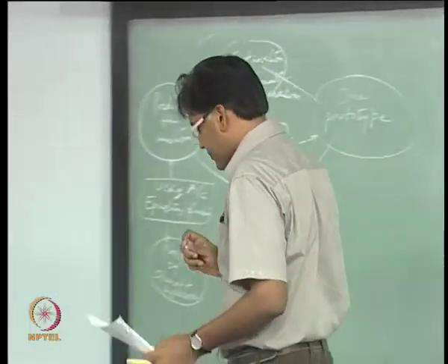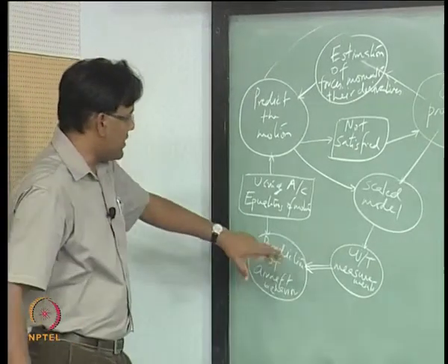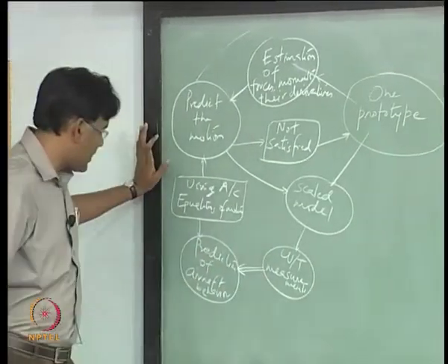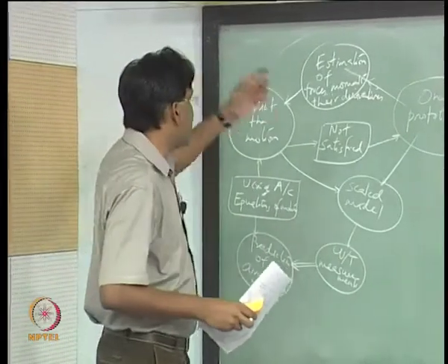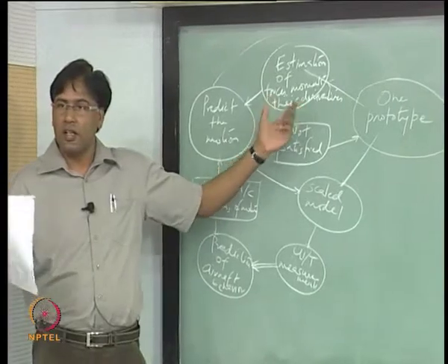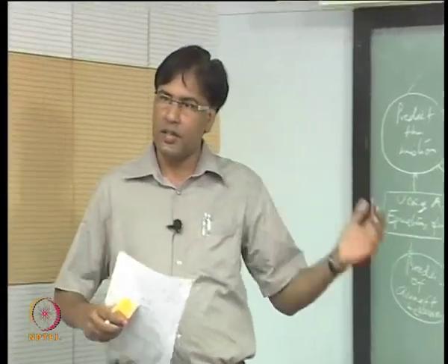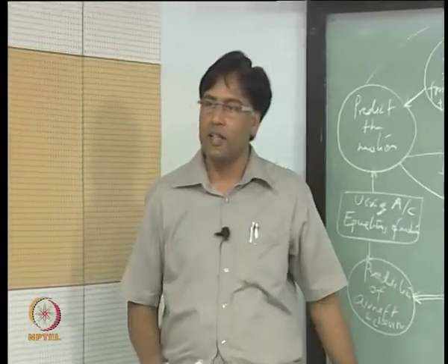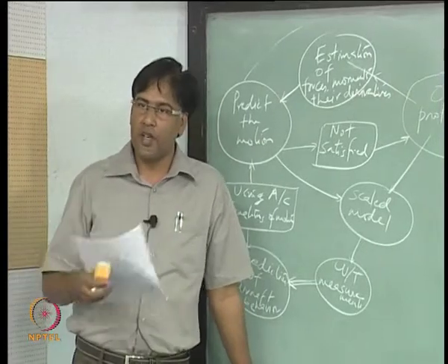And wind tunnel measurements will be for the scale down model, right. What here we are doing is we are looking at different components and trying to find the derivatives by adding the effect of contribution coming from different components.